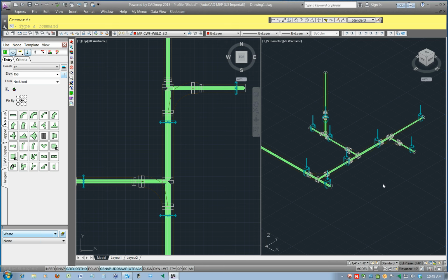Now the problem with editing: I usually delete my design line at this point because it's pitched now, and if I want to connect to this design line, I have to go back and unpitch everything, delete everything, unpitch it, and then I can draw my branches and then repitch it, and then I have to go back and delete everything again.